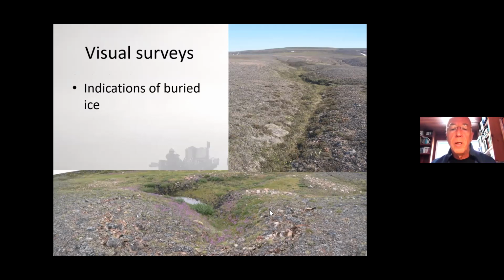That picture is the top of a moraine, a frontal moraine. And you can see here a depression that could be normal because these moraines are very irregular in shape. But when you see cracks in gravel that are fresh cracks, obviously there's something going on. This is settling, and if this is settling, that's because there's ice underneath. So there's buried ice under that moraine. And this, of course, is very important information to keep in mind.